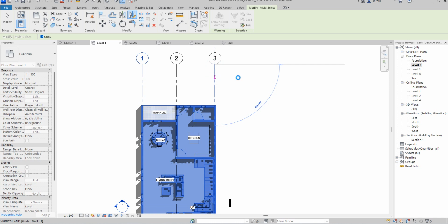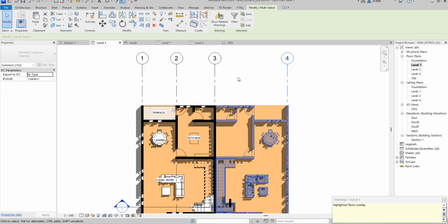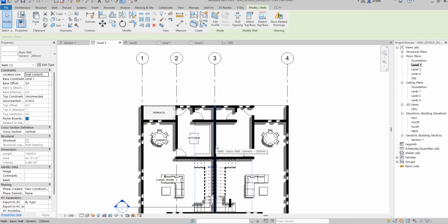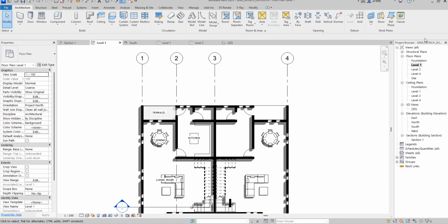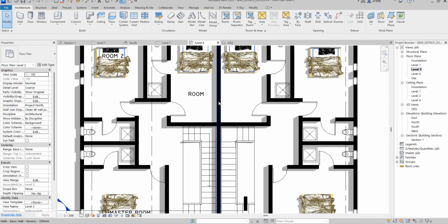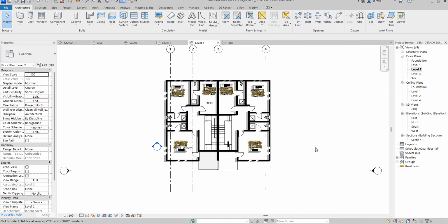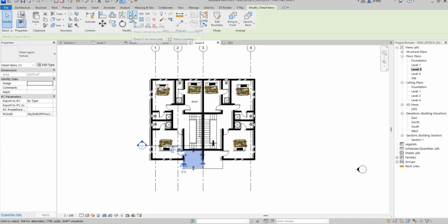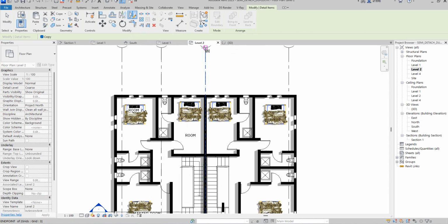So just mirror everything. It is going to mirror all the modeling you did; only the annotate will not follow through. So you can do the annotate on the plan level. So we've done this one now, which is okay. So the middle wall, we are going to delete because it's not needed. At level 1, then you go to level 2 and you delete the mirrored wall as well. Good. So the annotate, you just need to mirror the way you did it as well.